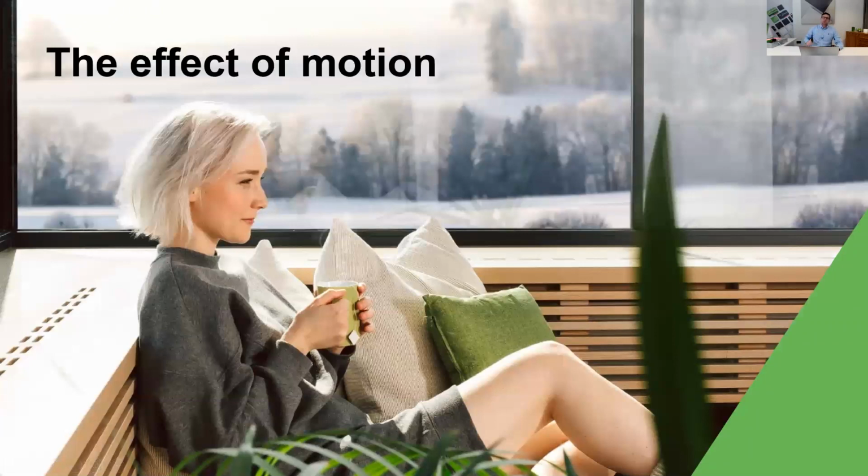And then I showed you the motion sensor on an earlier slide. So now we need to understand how motion comes into effect with room climate and with heating. Now, you would never use motion to bring on heating. The reason being is that it's just too much of a delay after the heating source turns on before it has any real effect in a room. Especially in something like underfloor heating, that could be 3 or 4 hours before there's actually an effect in the room of it turning on. So you never use motion to turn on heating.